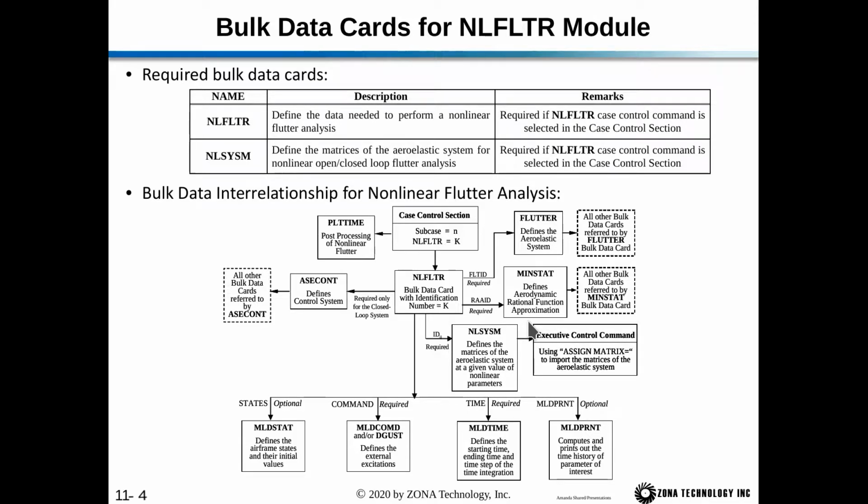Obviously, being a nonlinear analysis, a frequency domain analysis is not available. And then the nonlinear flutter card refers to the flutter bulk data card to define the aeroelastic system. Lastly, the nonlinear flutter card refers to the nonlinear system matrix cards. These define the matrices of the aeroelastic system at a given value of nonlinear parameters.